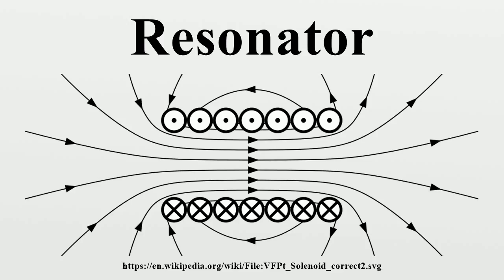Cavity resonators. A cavity resonator is a hollow closed conductor such as a metal box or a cavity within a metal block, containing electromagnetic waves reflecting back and forth between the cavity's walls. When a source of radio waves at one of the cavity's resonant frequencies is applied, the oppositely moving waves form standing waves, and the cavity stores electromagnetic energy. Since the cavity's lowest resonant frequency, the fundamental frequency, is that at which the width of the cavity is equal to a half wavelength,